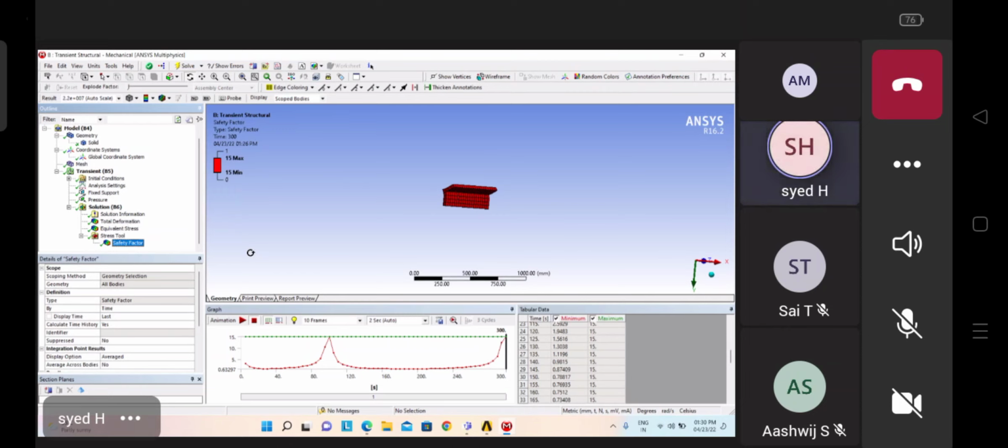Otherwise it will not. For example, if you are getting the stress value 260, if the yield point is 350, then we can say that the analysis is passing, like the test is passing here. Otherwise, we can say that it is not passing. The object is getting failed if it is crossing the 300 limit. So like that, there are some factor of safety values. Okay, understand?